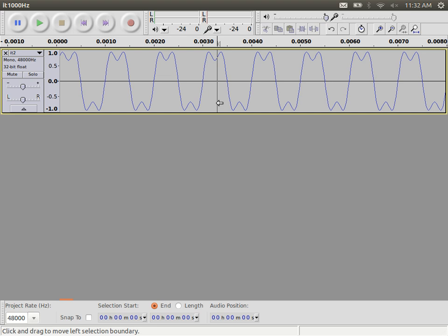Although it's not this signal, it looks the same. In 1 period, that is the highlighted area, we have a high level and a low level, each representing a bit, so we could transmit 2 bits in 1 period. 1 period is half a millisecond.